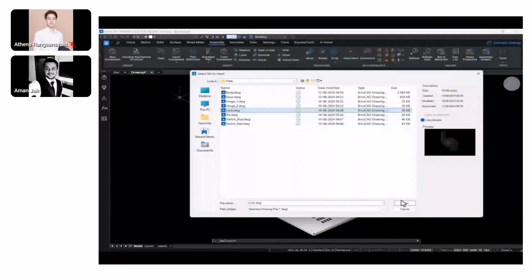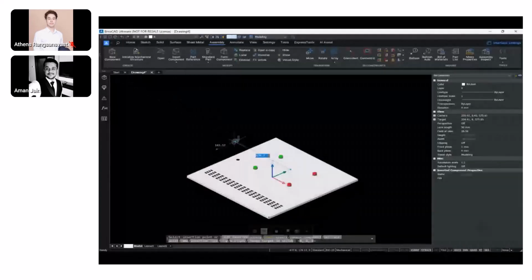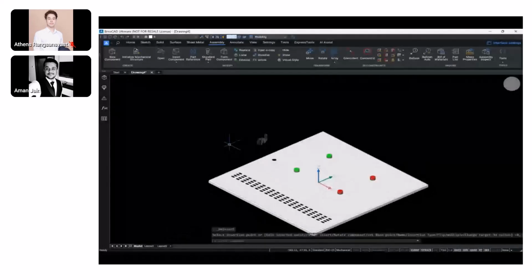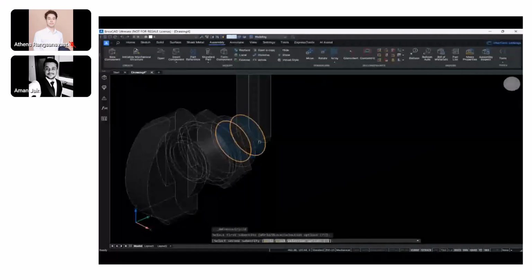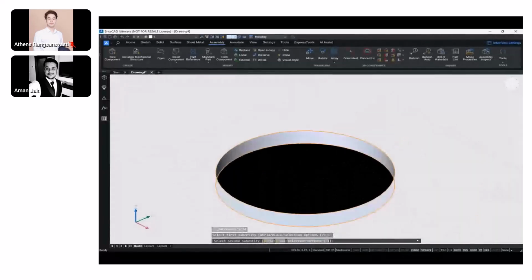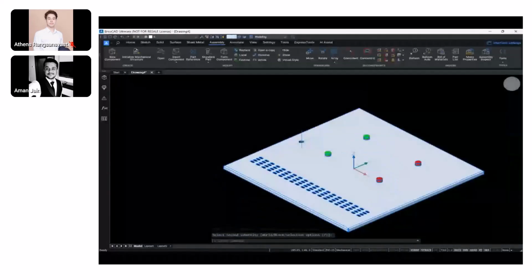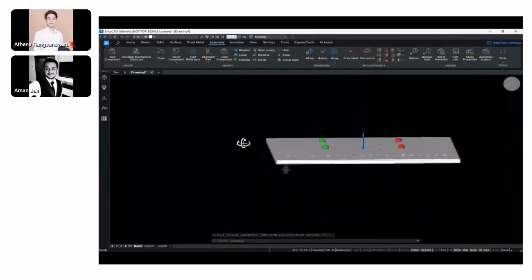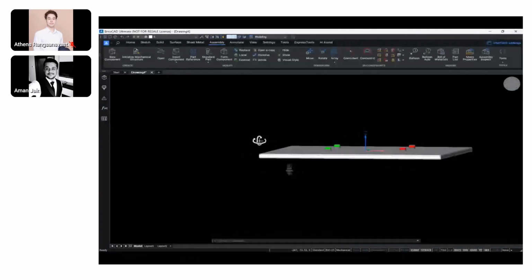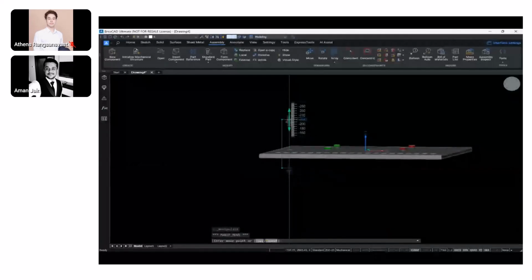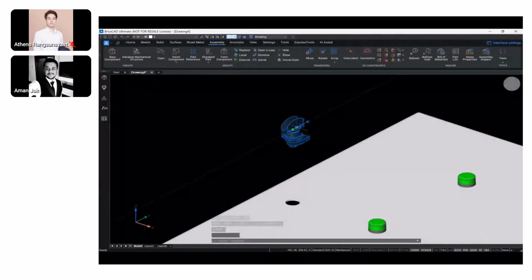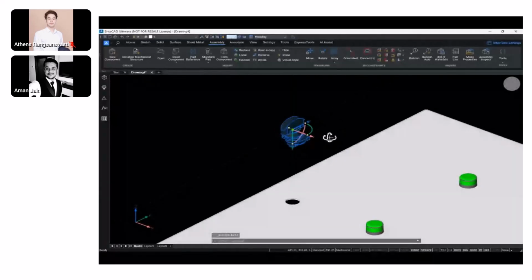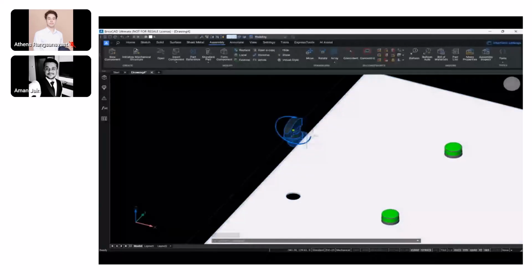The last part for this one would be the lock. I just place it over here, make it, let's say, constraint ready. Probably just rotate it, or I can directly apply the constraints as well. So just concentric for this one and for this one. Right? And there's this. Okay, now it's got a bit inverted. So I can just shift it upwards. We need the handle to be there on the outside. So let me see if I can use the gizmo to rotate it. So that would be this particular axis of rotation.